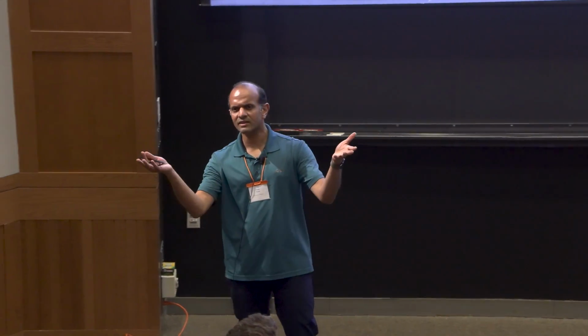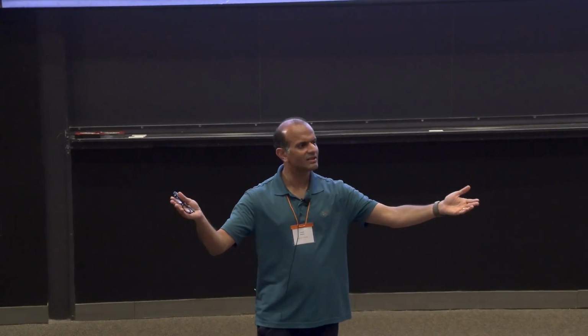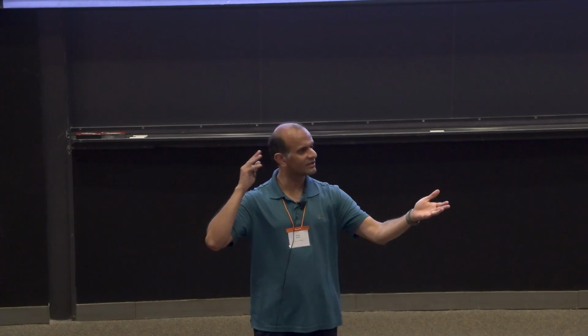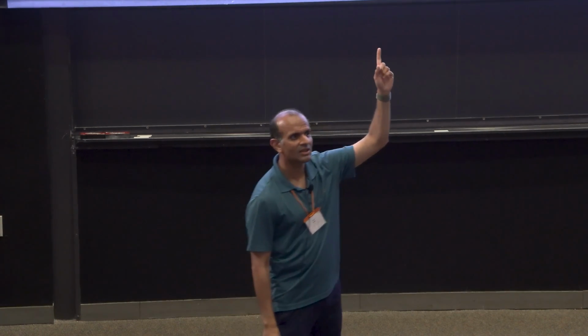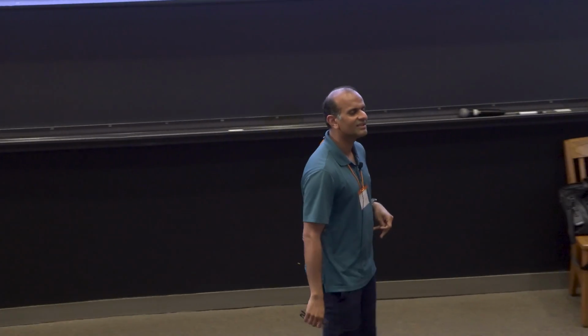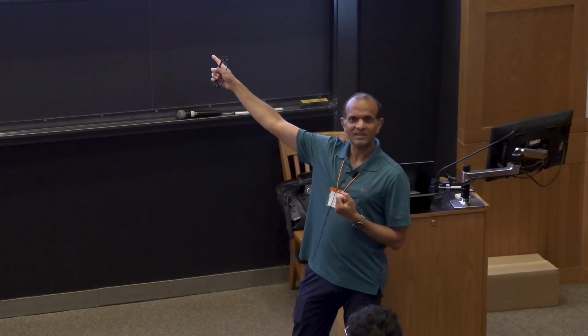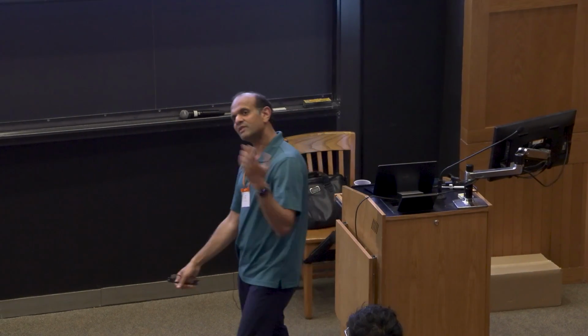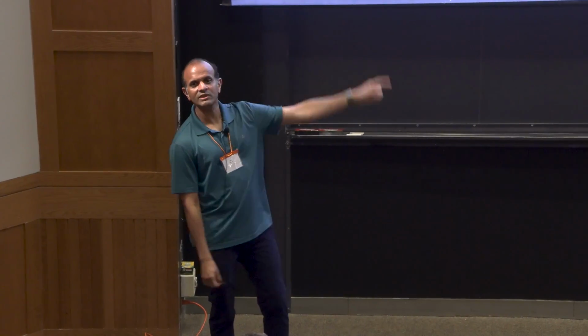Y_i is the mass fraction. What happens if I sum up the mass fractions? It's conservation of mass. So the sum of Y_i is 1. If I add all the equations, I should get the continuity equation, which is the first one. But will you get it? You won't get it, because the diffusion term has this D_i, it won't cancel. So I've assumed incorrectly that these species equations are consistent with the continuity equation.